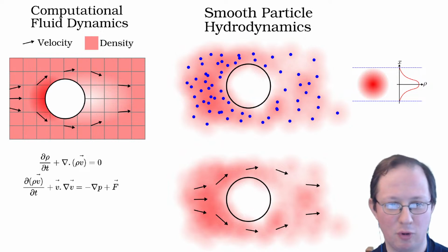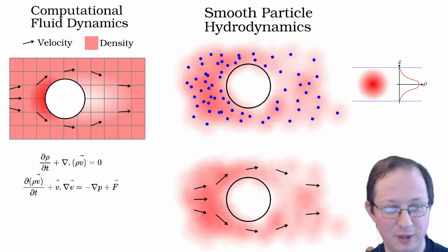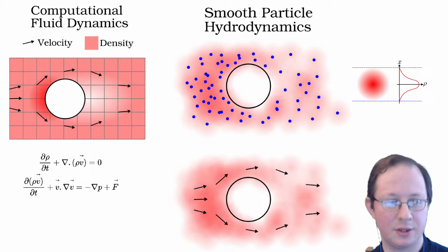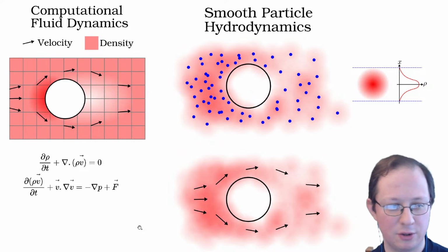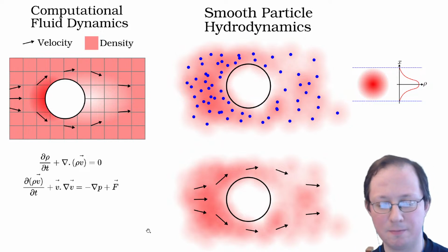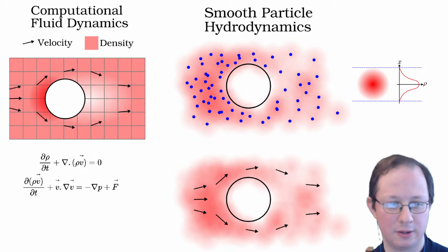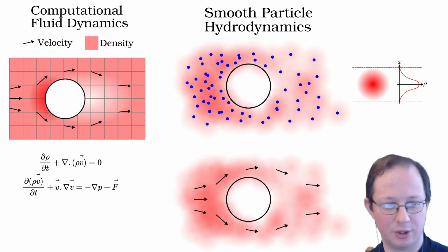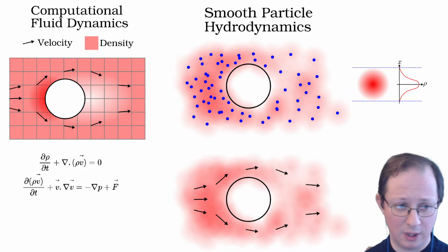The Lattice Boltzmann is more like the left. It's actually neither one of these exactly, right? It's more like the grid methods. You have a grid in FluidX3D, right? Exactly, it is a grid-based method. But it's not quite either of these because you're not solving Navier-Stokes exactly or directly. You're kind of indirectly solving them. You're solving the Boltzmann equation, which is equivalent to Navier-Stokes, but a little bit different because the discretization is different. So you have a grid, and that's what FluidX3D has.